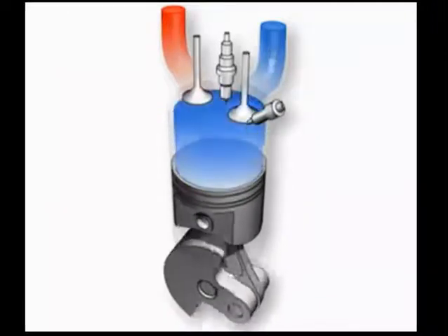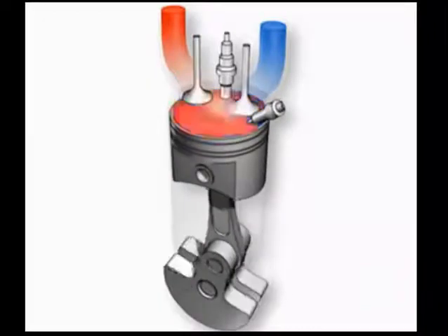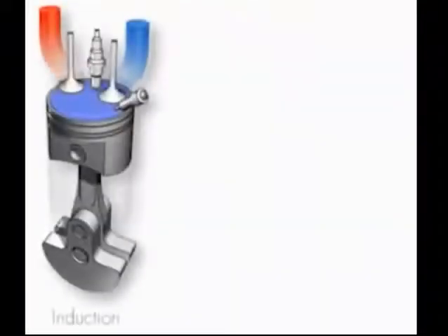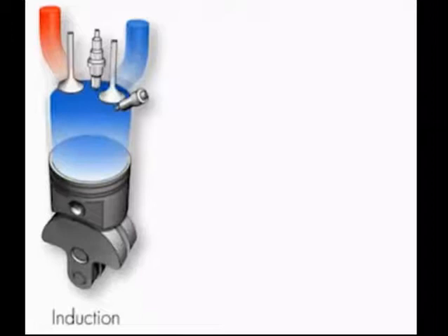In the animation, we show you the 4 working strokes: induction, compression, expansion, and ejection. First stroke, induction. On spark ignition engines, the air-fuel mixture is routed as a mixture into the cylinder during induction. In the case of direct injection engines, such as that shown here, fuel supply is by direct injection into the combustion chamber. On diesel engines, too, only air is inducted.